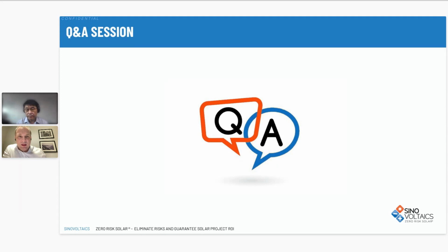Great. So next question is, thanks for the excellent presentation. What's the resolution of the EL imaging when taking from the drone? Can you see micro cracks? And also, can you do your EL under the full moon? Well, under the full moon, it's possible. We have a filter in front of our camera that can remove the ambient light. So this is not an issue.